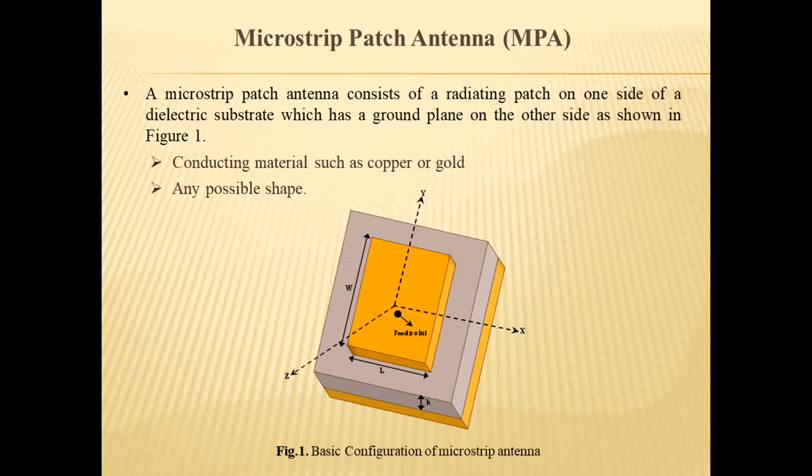For microstrip patch antenna, the selection of optimal design parameters such as patch length, patch width, substrate thickness, dielectric constant, and suitable feeding method to operate over the targeted frequency and over extended bandwidth is a highly iterative task. With this motive, data-driven machine learning-based methods have been proposed to estimate suitable set of design parameters for microstrip patch antenna, especially to be used for ultra-wideband applications. Some of the key methods such as neuro-computing concepts perform design parameter estimation.